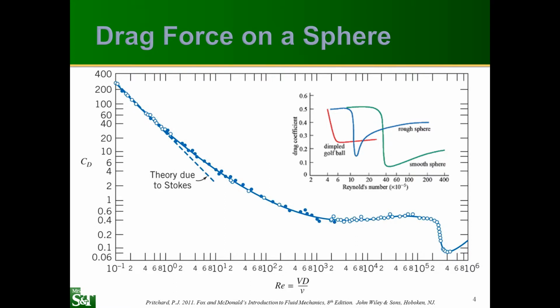It's only due to viscous forces. It's important to note that this component of the drag force decreases very rapidly. In fact, once the Reynolds number gets to be above 10 or 20, almost all of the drag force is due to pressure forces rather than shear forces.